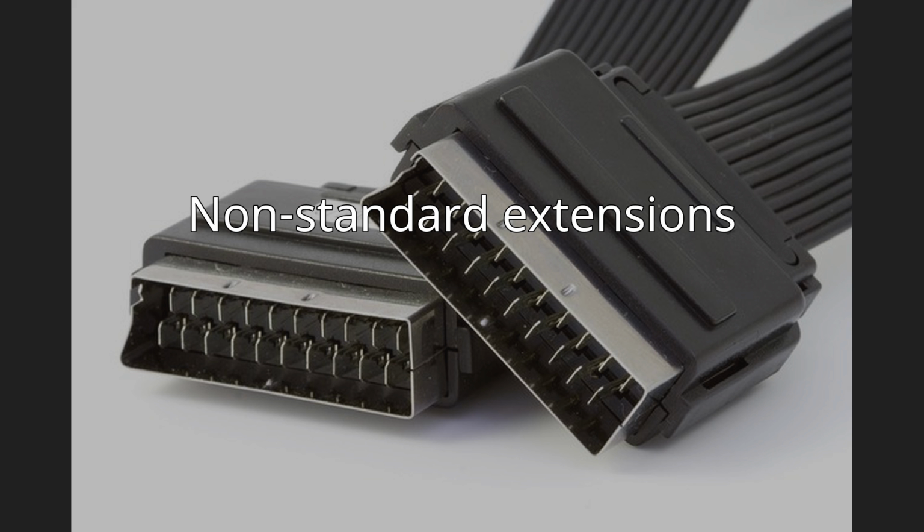The data pins 10, 12, 14 were used by some manufacturers for Dolby Pro Logic. However, this protocol was rarely used as it was limited to certain manufacturers, and the connections were different from one manufacturer to another, and in some cases it was only commanded by pin 8. In this case, it was unusable with RCA to Scart adapters.